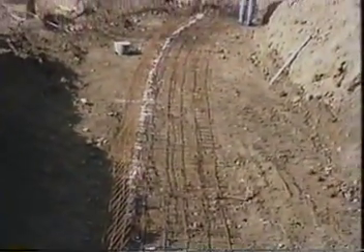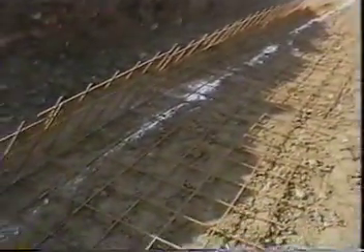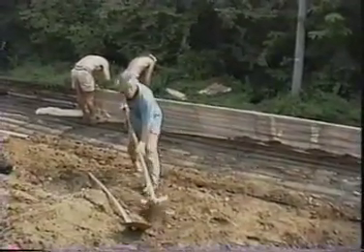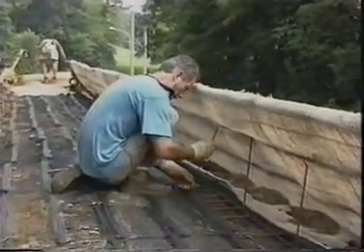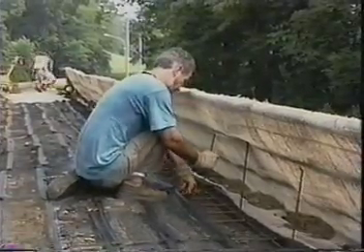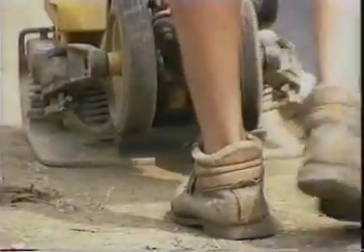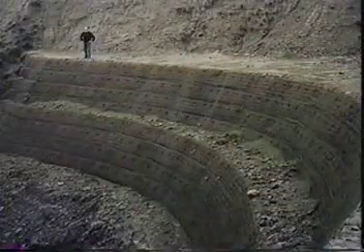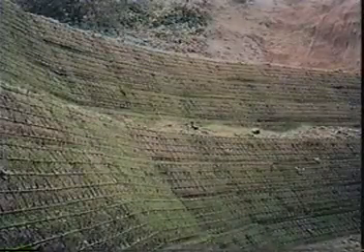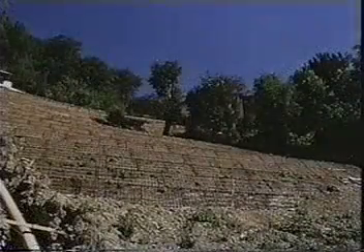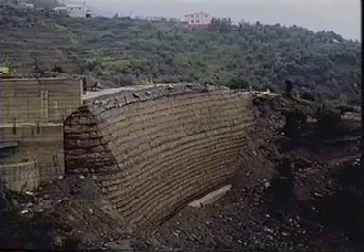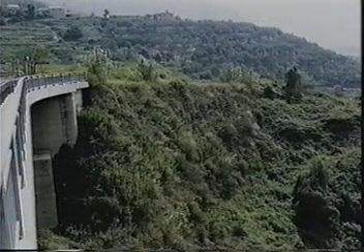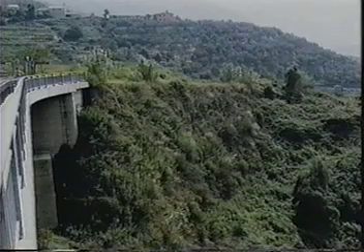This type of steel grid facing is a slightly different version of the caged facing. With an inclined arm bent to a predetermined angle, a planar slope can be constructed. The grids also provide formwork that allows the fill to be compacted right up to the required line. These cages stabilize the face over the design life of the slope or wall, especially against the effects of erosion. The steel grid may also be used purely as a construction expedient that is allowed to corrode within the design life. As plants and bushes take hold, their roots contribute to long-term slope stability.